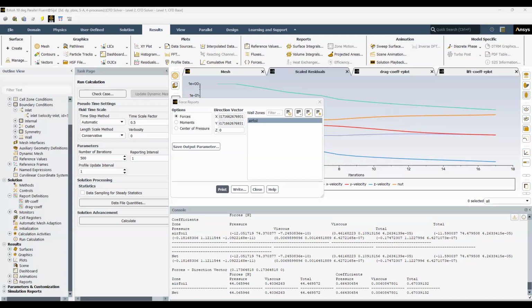One will be the x component and one will be the y component, okay. For the x component, it will be with the angle of attack, so cos 10, and here it will be sine 10. Simple. Sorry, not here, but this angle of attack 10 degrees. So in the x value, we have cos 10, and the y component we are going to have sine 10.